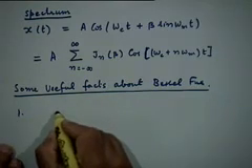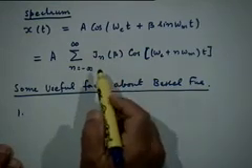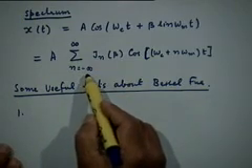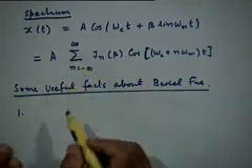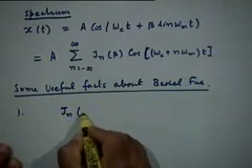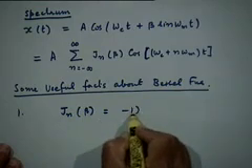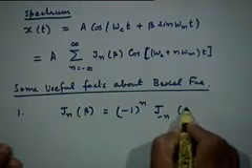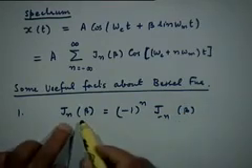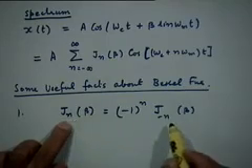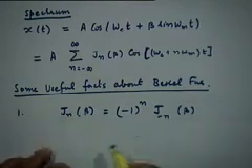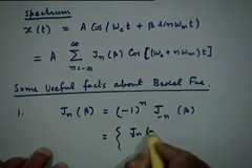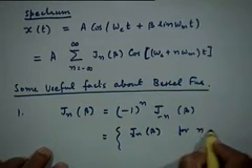First, there is a kind of symmetry in these functions as a function of n, right. In the series expansion you have n going from minus infinity to plus infinity, right. Now it can be shown that J n beta is equal to minus 1 to the power n into J minus n beta. So this is how the Bessel functions of order n and order minus n are related, right. What this means is this is equal to J n beta or J minus n beta for n even